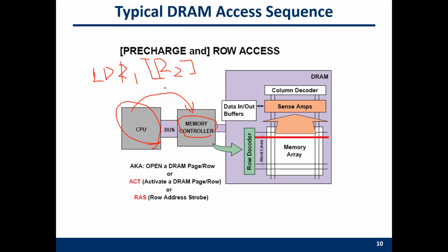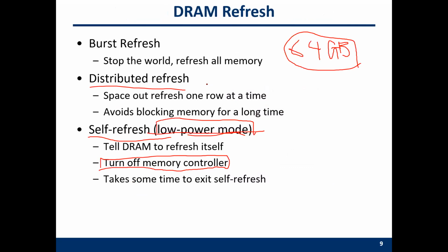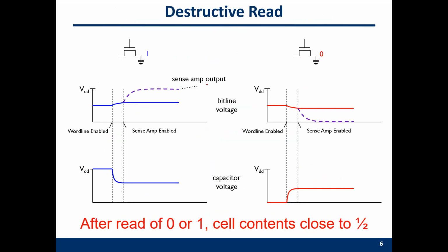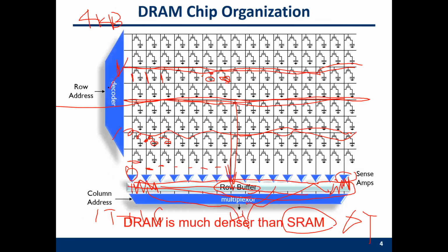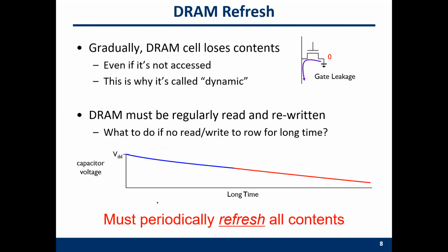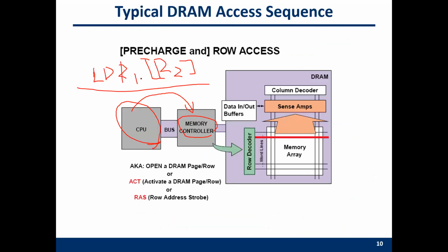Memory controller will translate this instruction to what? To the command which the DRAM can understand. The DRAM can only understand, for example, activate one row, send the data to the row buffer, restore, refresh, or use column access to read a part of the row buffer. So DRAM can only understand these simple commands. And your memory controller is actually a translator which can translate the real instruction to the DRAM instruction.